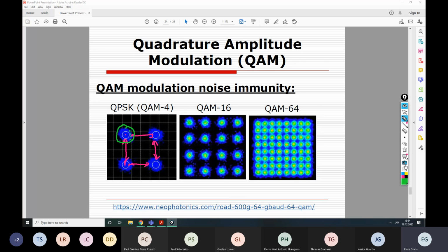And then the detector, the optimal receiver, works in a very simple way. It calculates, for example, let me mark this point, right? So what does the receiver do? Basically it calculates 4 distances. Distance to here, distance to here, here, and here. And then it chooses the shortest distance and assumes that, okay, that means that the data transmitted was, for example, 0, 0. I'm assuming that 0, 0 was assigned to this point, but it could have been another thing.